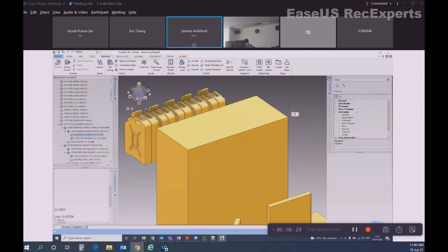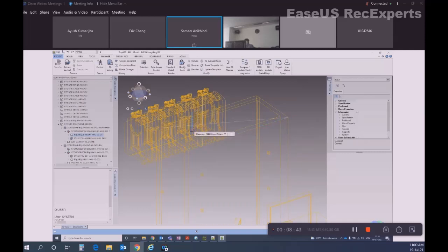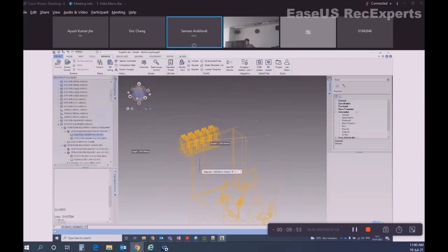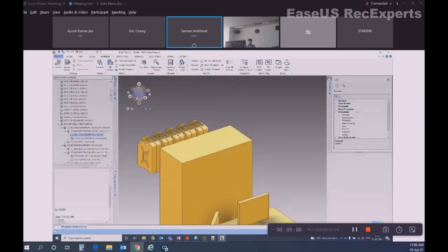For example, if I use DI again, shift right click, I will just use corner snap, corner from here to here. So it will just show me this distance. It will not give me northing, easting or angle. It was showing. So if I press F12, it will give me other inputs also. So let me start again with dynamic hints on. So I will use DI.